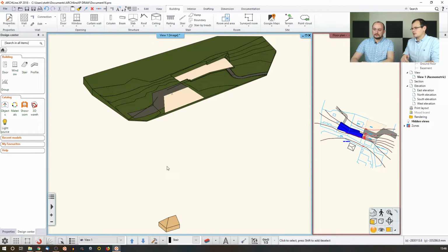So if you are going to draw additional walls or elements in this drawing, they are going to be put down at the 0 level, far below the model. Now, how do you bring them to a common ground? And this same thing happens when you already have a building and you import terrain. They are not necessarily matched together already. Yes, because this is not controlled by the terrain. It's controlled by the elevation settings of your project. If you do not set up the elevation settings of your project, everything that you create lands at 0. Except the terrain, because in the case of designing the terrain, you already tell where it is.